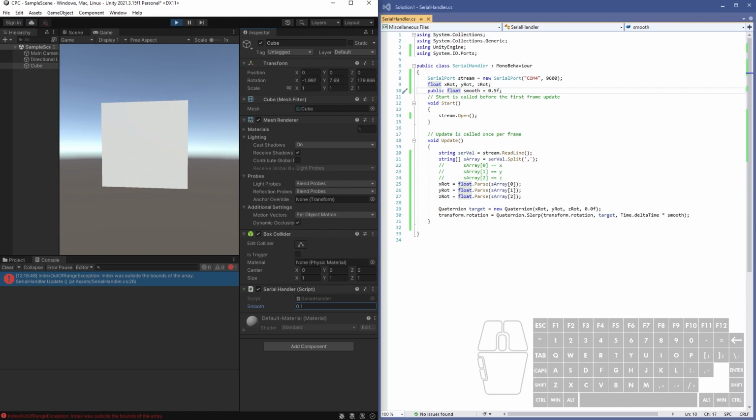Or you might use the capacitive touch sensors to create a custom video game controller. It's really up to you, but I hope this tutorial has demonstrated that it's all relatively simple. You're just grabbing data from the Circuit Playground, labeling it, and pushing it through serial, then essentially decoding that serial to be used as variables within your application.